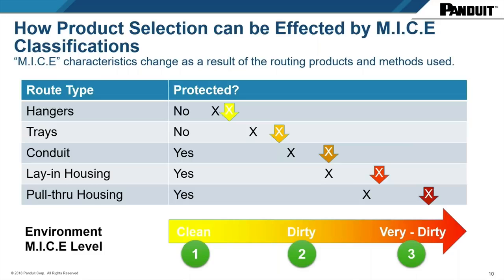So how do we protect our cables? If you put your cable inside of a conduit system, then you're basically changing what you call a commercial grade type cable. If you put it inside of a conduit, you give it an additional protection so it can take a dirtier environment because the conduit is protecting it. You have to worry about condensation, and that could be an issue. So when you start running cables inside of the factory, you need to be made aware what the hazards are and what type of route type I need to apply to run my cables in. And that is how we go about doing this.